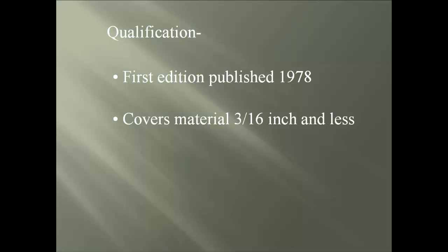The scope covers the arc welding of structural sheet strip steels that include cold forming members with a thickness of 3/16 inch and less. When sheet steel members are joined to material 1/8 inch and thicker by welding, Annex A must be reviewed for conformance.